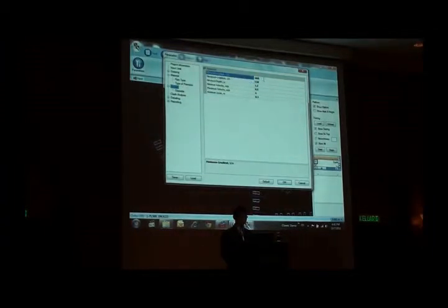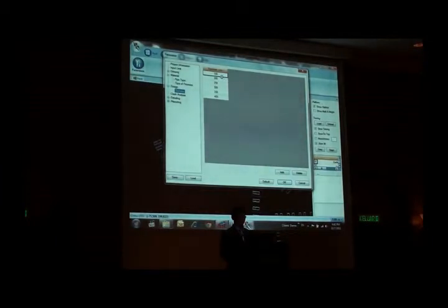We have this. You can adjust the minimum maximum gradient, the depth, the velocity, everything you can adjust. Then the diameter. So we can propose the minimum diameter. This is a 150. If the diameter cannot pass, we go to 200 up to 400. If 400 still cannot pass, then the program will put out an error message, unless we add in more.